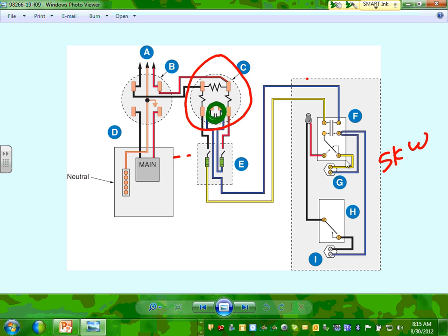So if they can control this one. This is what it's called off-peak. For example, at midnight when nobody's turning power on, they can turn it on and heat the water at night. They can turn it off when people come home, say 4 to 7, 8, 9 o'clock. This is peak. In the morning when people get up, and in the middle of the day when factories are running, these are peaks. Morning and evening are peaks.